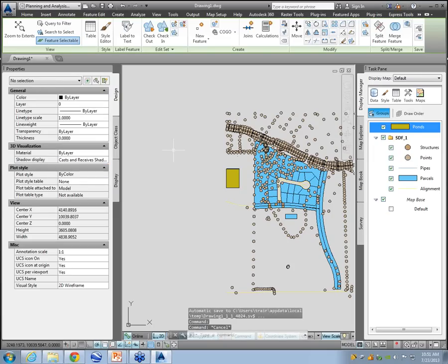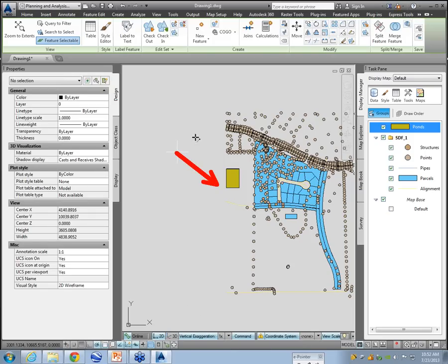Okay. Last thing, of course, if you've worked with this stuff before, when you're done working with everything, or every so often, you're going to want to reach up here and hit check in. As soon as you check in, you can't undo anything that you've done, but it pushes it down to the file. Now, if you do not check in and your computer crashes, don't panic. If you open up this drawing again, more than likely, those objects will still be checked out because they're not tied to this anymore. They're actually on my computer somewhere in my C drive, and they're cached.